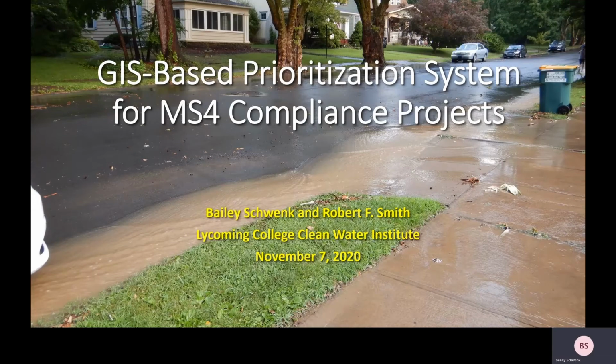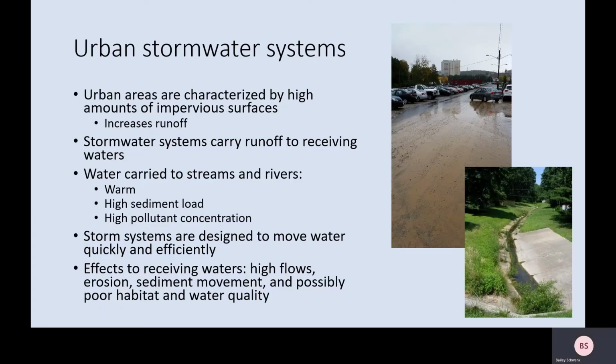My name is Bailey Schwenk, and today I will be talking about my research creating a GIS-based prioritization system for MS4 compliance projects. Urban areas are characterized by their high amount of impervious surface. This high amount of impervious surface increases the amount of runoff in the system.